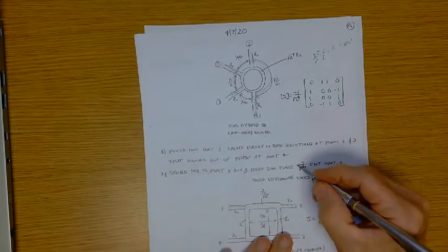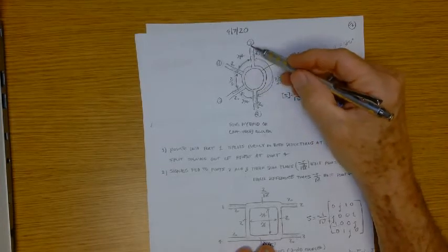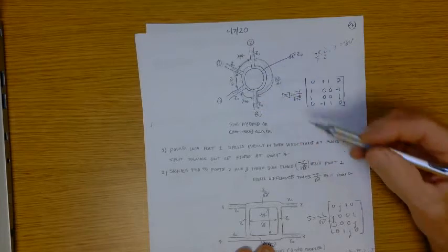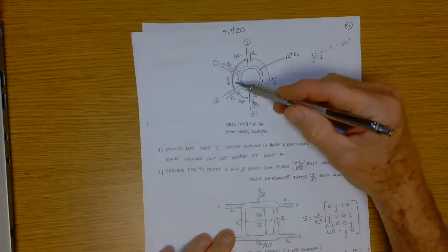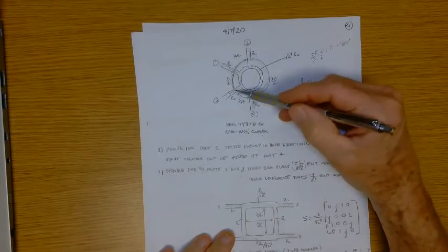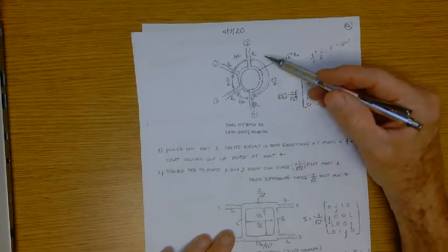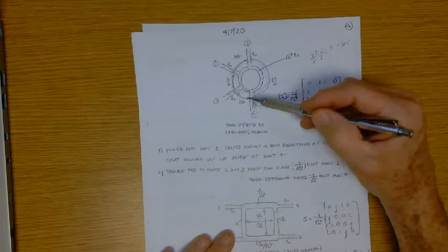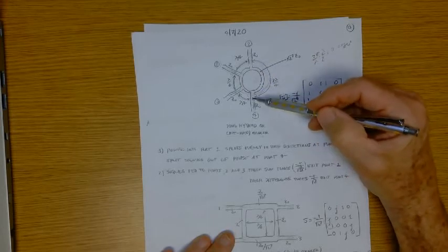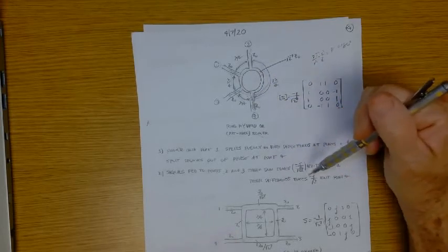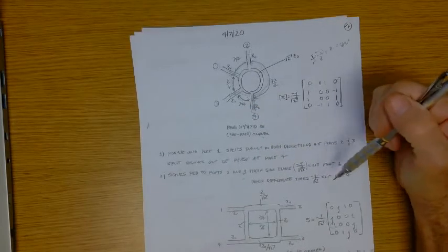So this is just a multiplicative factor, right? And then their differences, right? If I put signals into 2 and into 3, the difference exits port 4, comes out of port 4. Here and here, this is the difference signal, right? Because that's 3 lambda over 4, that's lambda over 4. So again, there's a half wavelength between these two, and so that's the difference between the two signals, and then times minus j divided by the square root of 2.